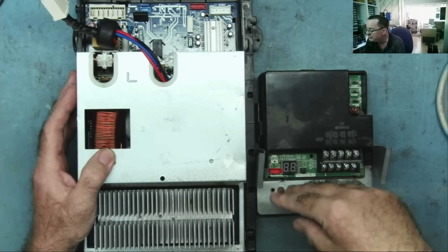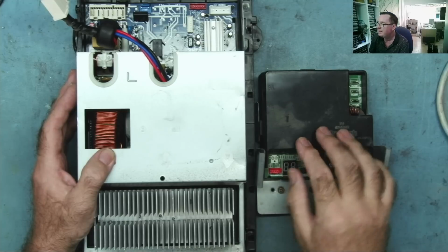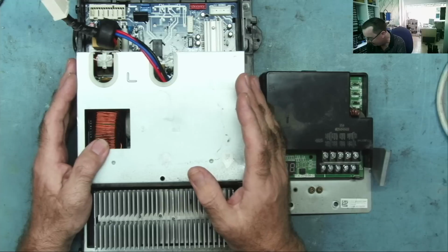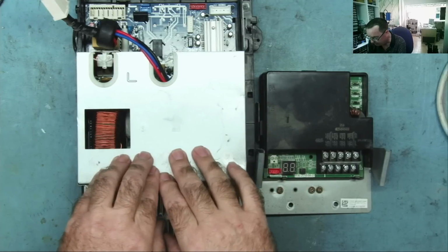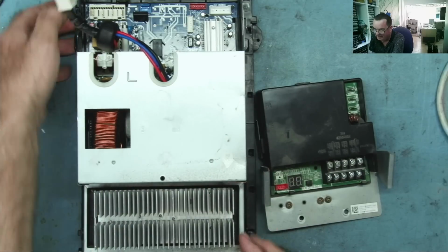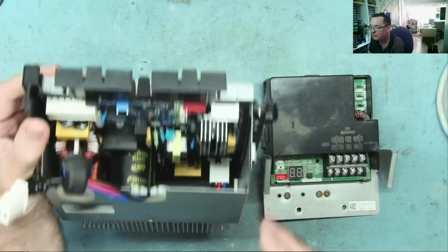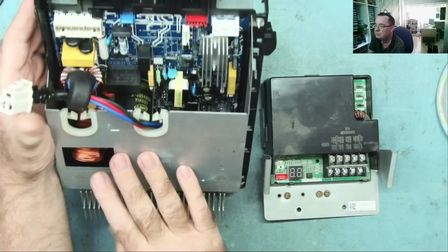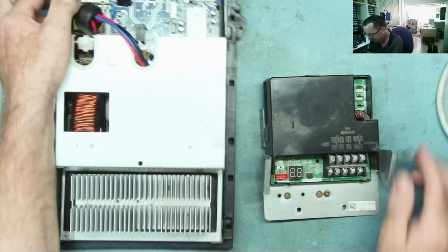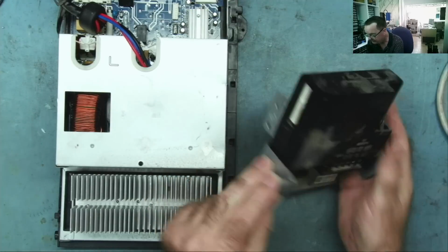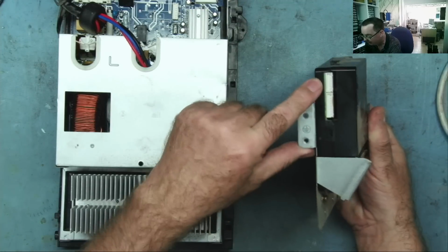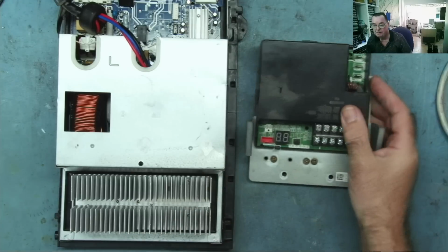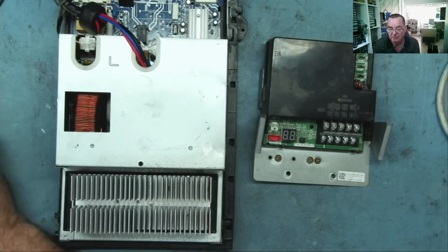I'll check first to see that the power is getting from here through here to this one. If that is the case, then I'll have a look at this. I think this has the actual power supply in, so we can see the large capacitors down here. I'm expecting this has some sort of switch mode power supply on here. This may also have, or it may get its power back in through here actually, that powers up the display. Okay, we have a plan at least.